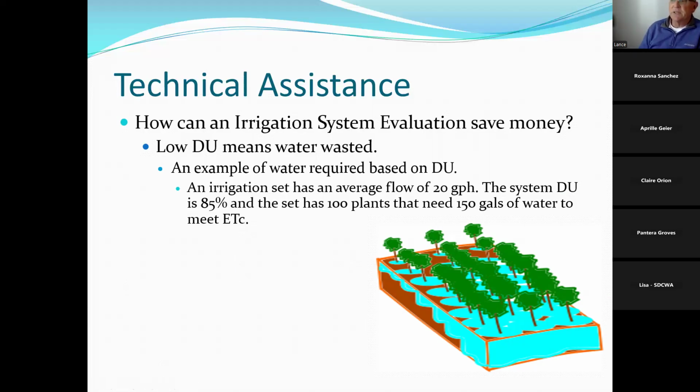Evapotranspiration is a measurement of how much water has moved through the plants primarily. That's the T, the transpiration. Evaporation is just water that is evaporated off the surface of the soil back into the atmosphere. With a micro irrigation system, the typical evaporation rate is only 1%. So most of the water has moved through the system, through the plants themselves.